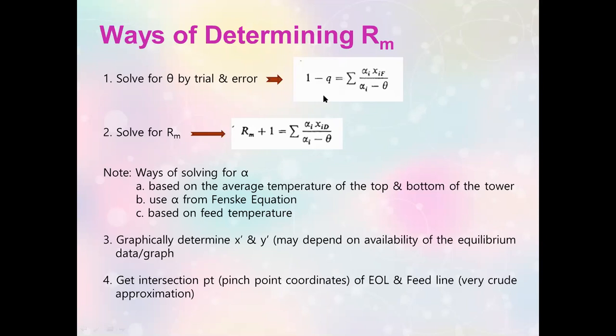R minimum. So you are already given the Q and you determine the theta from this particular formula. I will give you the procedure on how you find the theta out of this particular step. But the thing, class, is this one is trial and error. Let's say, for example, you know already and you already determined theta out of this. Of course, you need to know the Q.